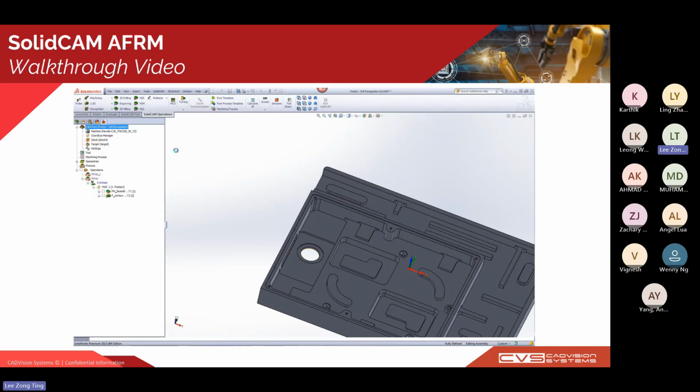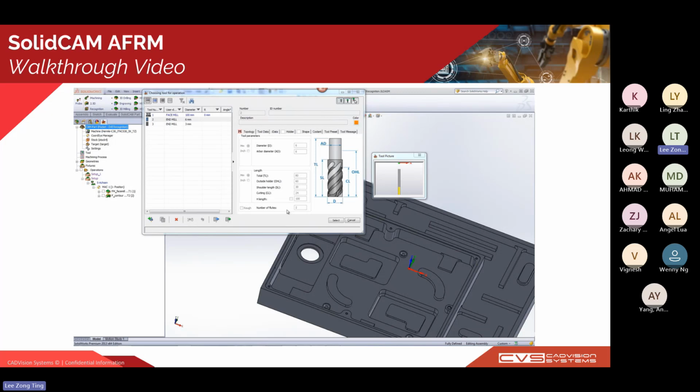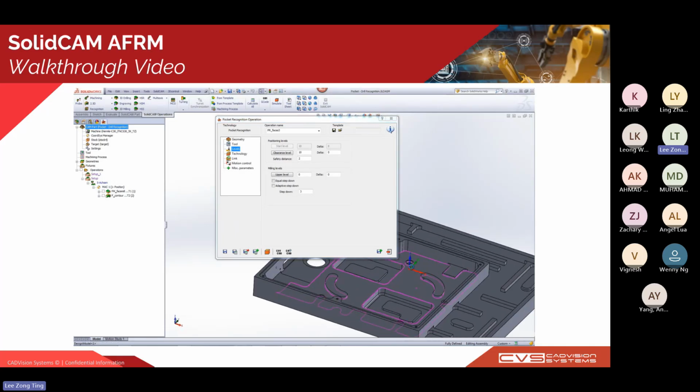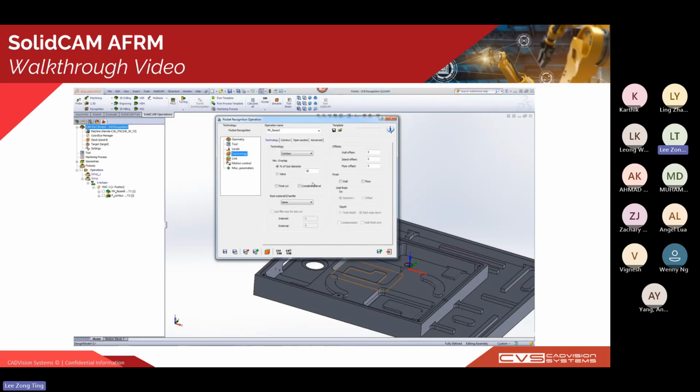And after you have all these pockets recognized already, then you can go ahead and do the same workflow like pocketing operations, which is selecting tools. And you can see in the levels also. So typically we will need to specify the depth of the cut. But in here we can see there's no depth of the cut. We can only choose the upper level because there's different types of pockets within these solid bodies. So it will automatically compute this depth and pass it back to these operations. So we cannot specify how deep we want our cut to be because it is automatically recognized from the AFRM module already.